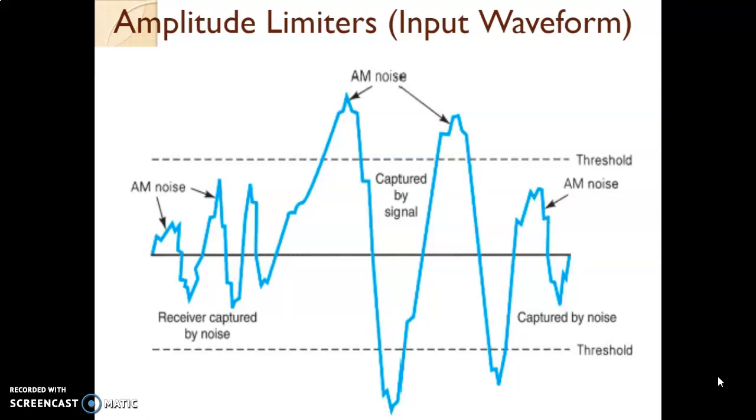We have talked about amplitude limiter somewhere during the demodulators, and we said that the ratio detector is the one circuit which is going to provide amplitude limiting by connecting a large value capacitor at the output, but none of the other types of demodulator, that is the Foster-Seeley discriminator, single slope, and balanced slope detectors, are able to provide amplitude limiting. Now here we should discuss why amplitude limiting in FM becomes important, and in the receiver also this particular block is always present.